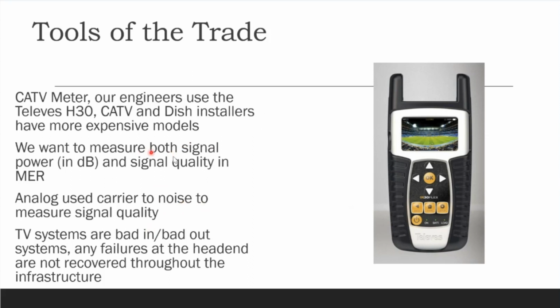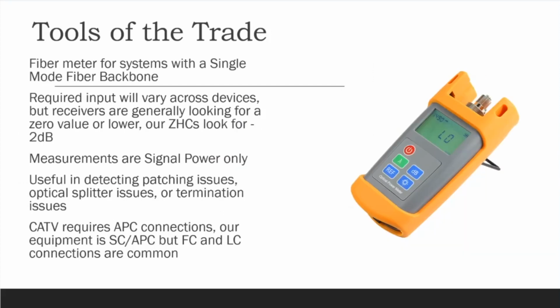So that is worth noting with digital, and it's a dead giveaway when we're troubleshooting clients. Anytime a client comes to me and says, hey, my TV's fuzzy, that's analog, because digital video is not capable of that. Digital video doesn't do fuzzy. It does pixelated, but not fuzzy. And so that's really what we're looking for in that RF meter. We are looking for not only the power, but the quality.